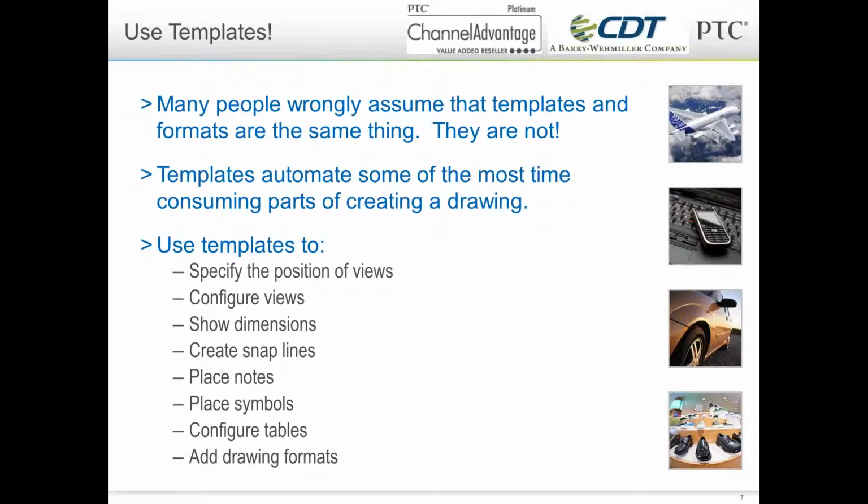But templates don't just apply formats. The underlying parts of the sheet are what we call the format. But templates also allow us to specify the position of views, to configure those views with specific things, such as showing dimensions and creating snap lines. I can automatically place notes and symbols and tables onto a drawing. And the one that most people already know about is using or adding drawing formats.